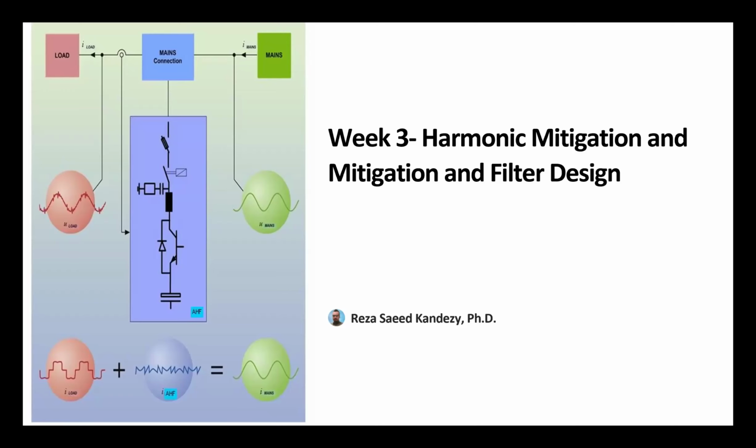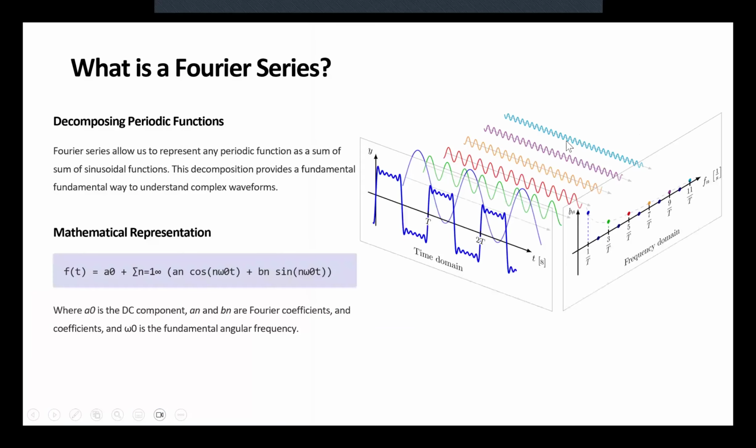However accurately we do the switching, we can never reach the point where, by switching, we get a pure sinusoidal voltage. At the end of the day, we are always switching on and off a DC voltage. So we are creating a bunch of square waves, adding them together, either in parallel or in series, and then trying to get close to our desired voltage. That means we always have a distortion.